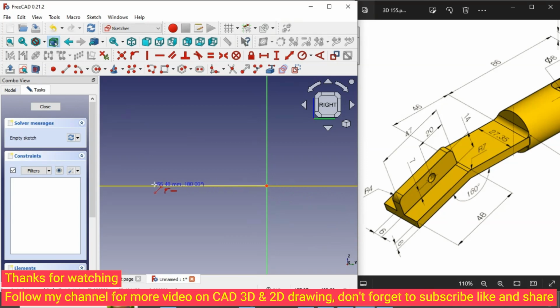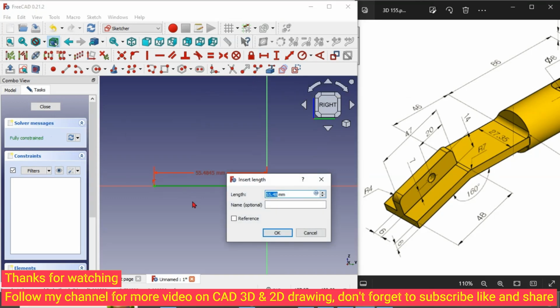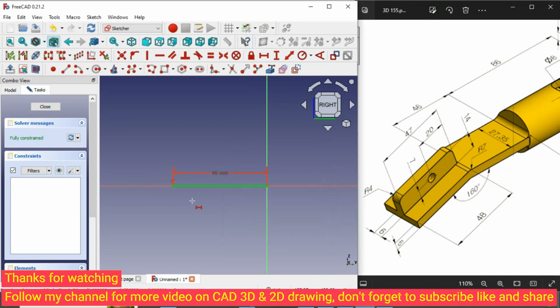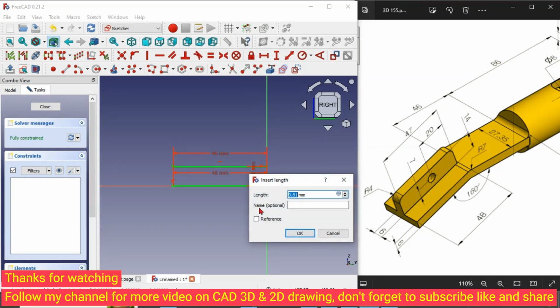and draw a line first from here to here, then we set the distance will be 46. We draw another line, dimension also 46. Then we make this line parallel with this center line here, then the vertical distance from this line to the center here will be 6, the thickness of this block.